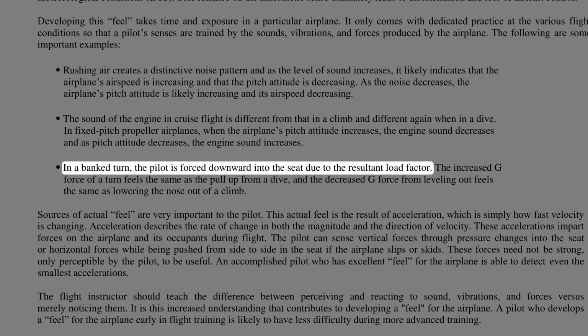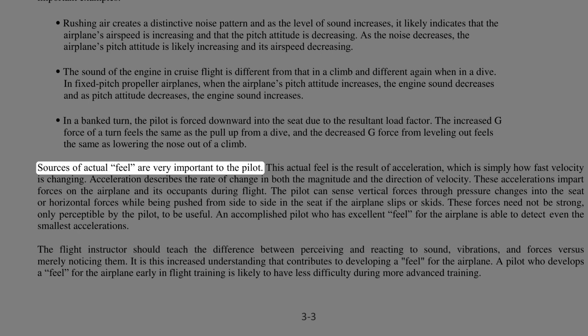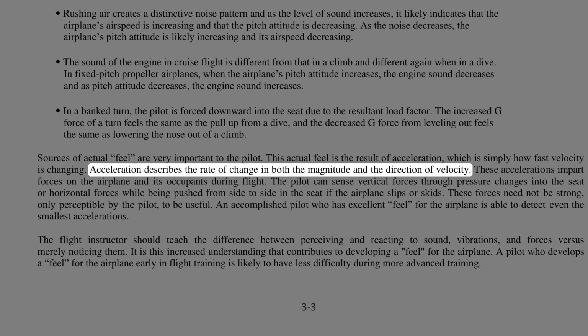In a bank turn, the pilot is forced downward into the seat due to the resultant load factor. The increased g-force of a turn feels the same as the pull-up from a dive, and the decreased g-force from leveling out feels the same as lowering the nose out of a climb. Sources of actual feel are very important to the pilot. This actual feel is the result of acceleration, which is simply how fast velocity is changing. Acceleration describes the rate of change in both the magnitude and the direction of velocity.